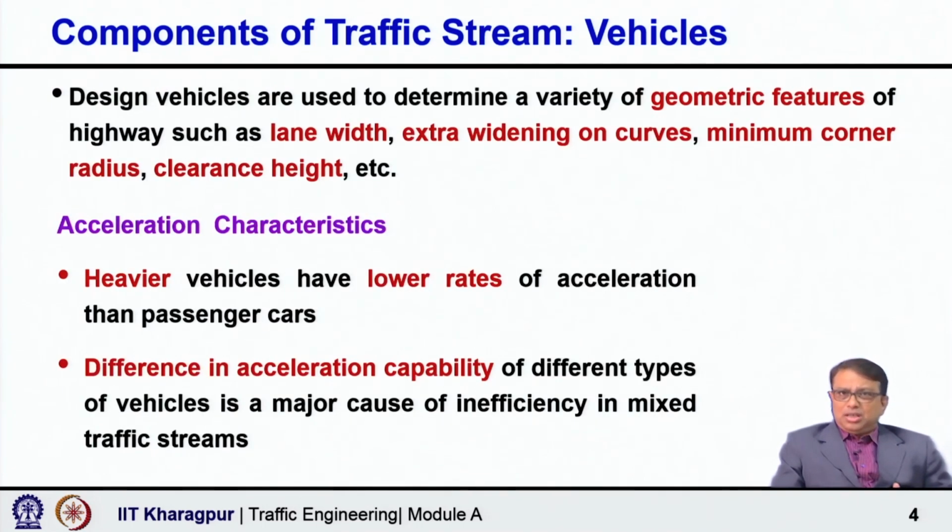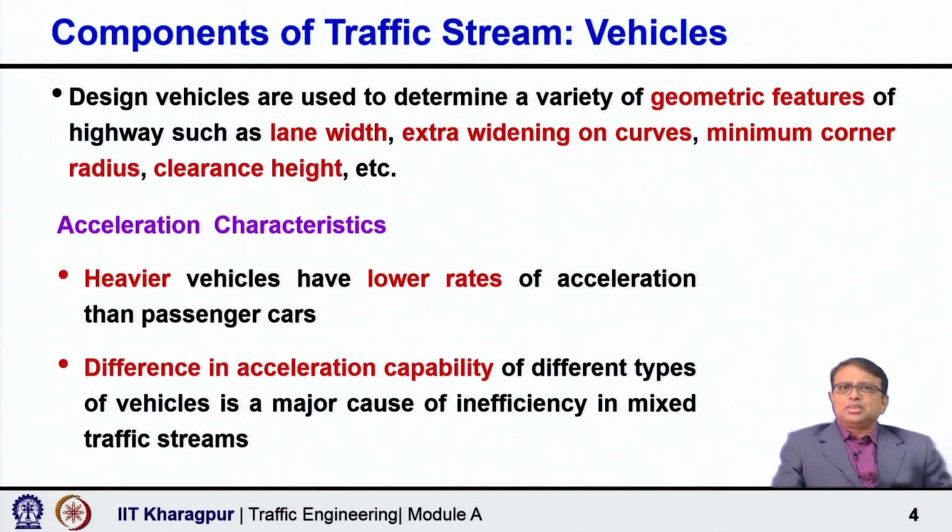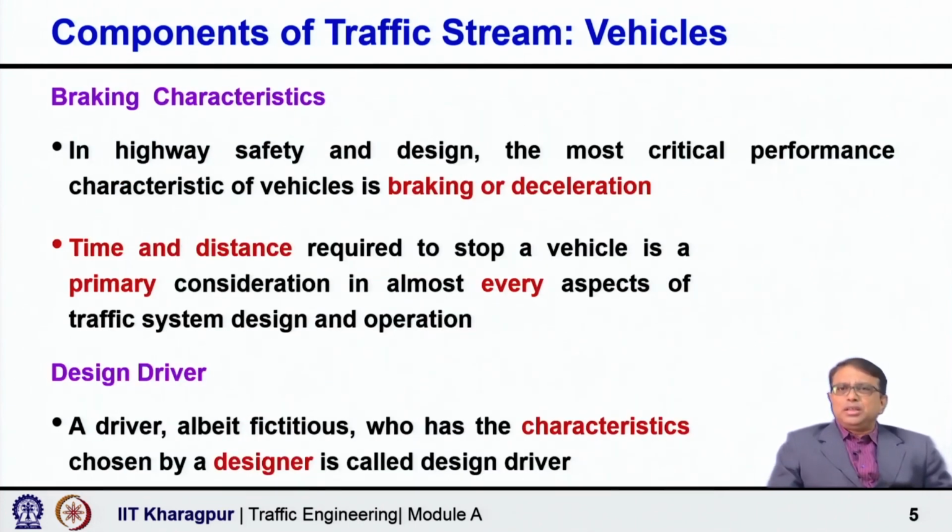So, we need to understand the vehicle characteristics first, and then acceleration characteristics, and also braking or deceleration characteristics. Then the next part is design driver. As there are variations in the vehicle characteristics, similarly the driver characteristics also vary, not all drivers are the same. So, as we bring in the concept of design vehicle, similarly the concept of design driver comes.